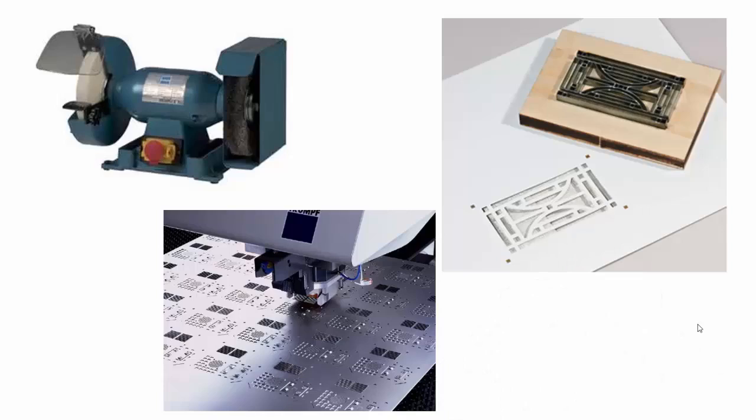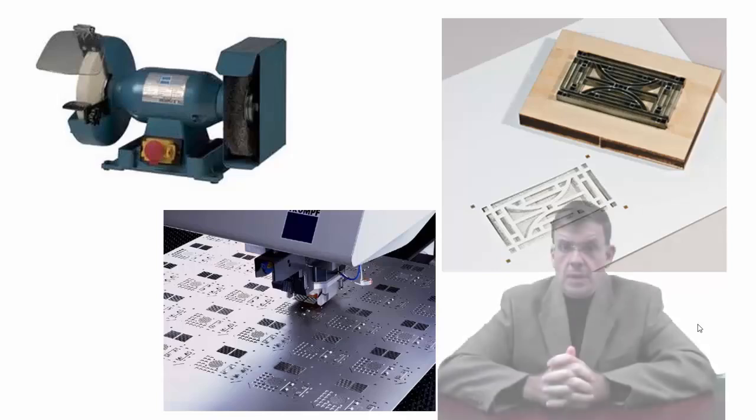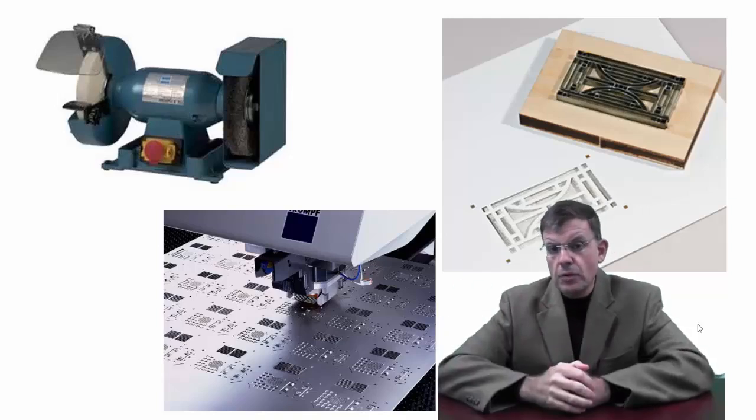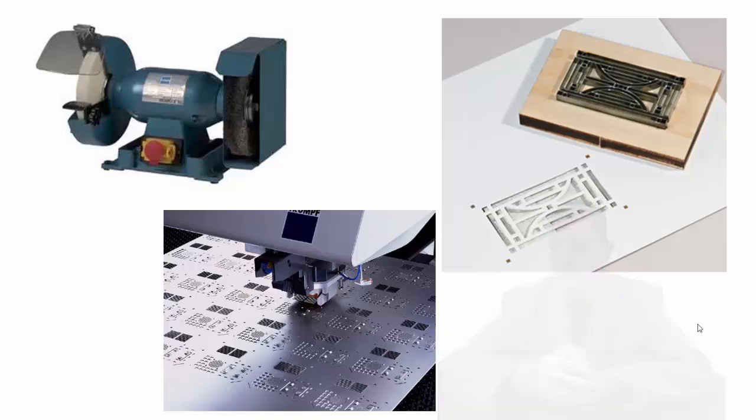On the right, you see an example of a die cutter. You see the die cutter itself mounted on a plank of wood, and those are very sharp pieces of metal that conform to the shape that is to be cut. And of course, this would be applicable to relatively soft materials or certainly thin materials. And again, if you were doing this in the context of sheet metal, then that would get its own technology and its own terminology.